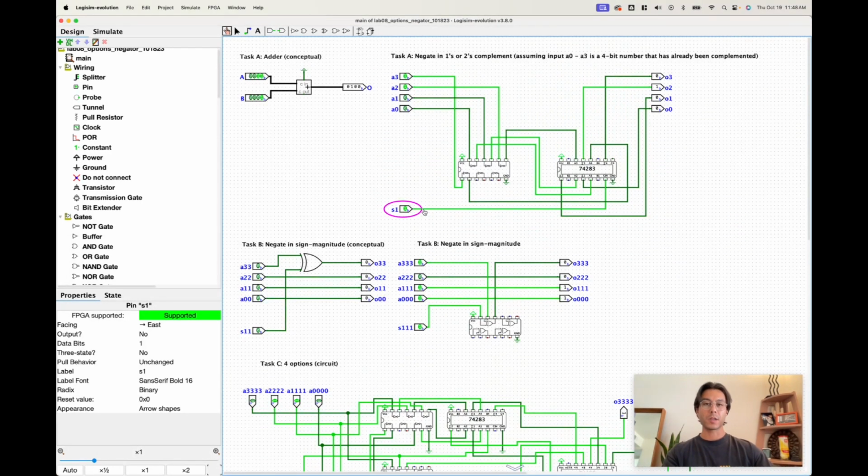From standard unsigned to ones complement, you flip all the digits to the opposite symbol, 1 to 0, 0 to 1. And for twos, you add the 1. So here we can see 1, 1, 0, 0, you add a 1, it equals 0, 1, 0, 0. When you put in 1, 1, 0, 1, and you don't add anything, well, that is the ones complement. So that is 0, 0, 1, 0. And again, ones complement is flipped. So 1, 1, 0, 1 flipped is 0, 0, 1, 0. The output is 0, 0, 1, 0. You add a 1, that goes to 0, 0, 1, 1.